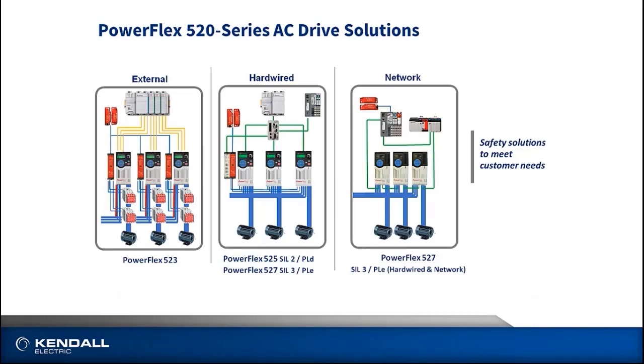That advanced into safe torque off inputs on the drive, which cut the ability of the transistors to fire on the output of the drive. This helped maintain the drives better than contactors, so they didn't burn up when we disconnected the power under full load, and it also allowed the drives to come to a safe torque off and actually disable the drive at the same time.